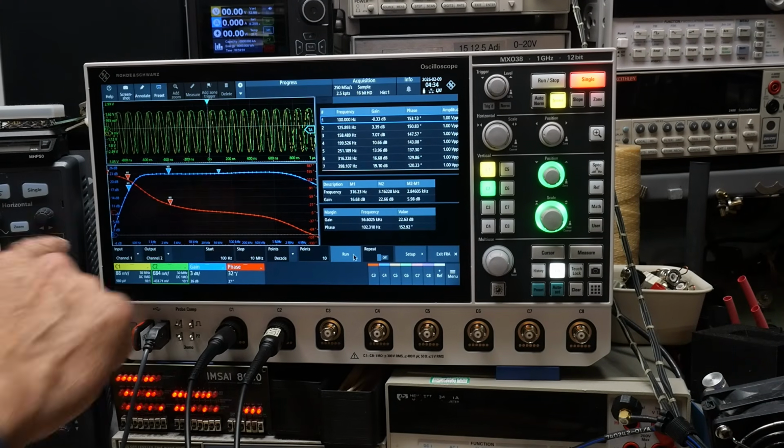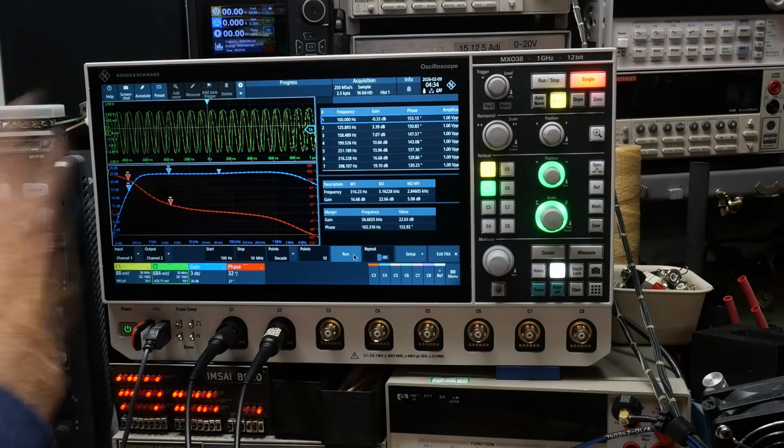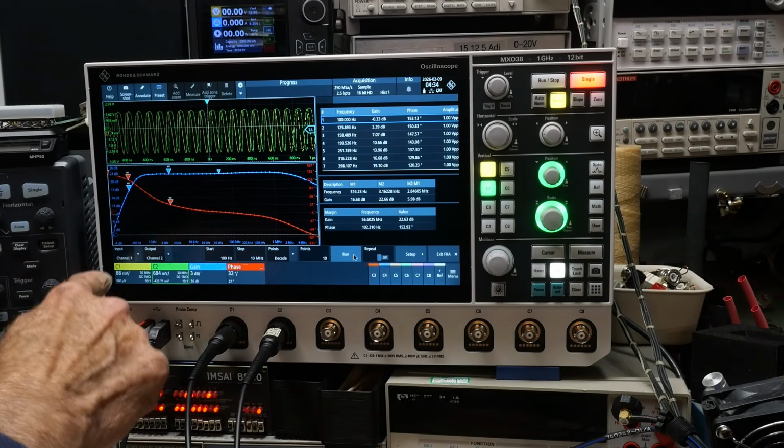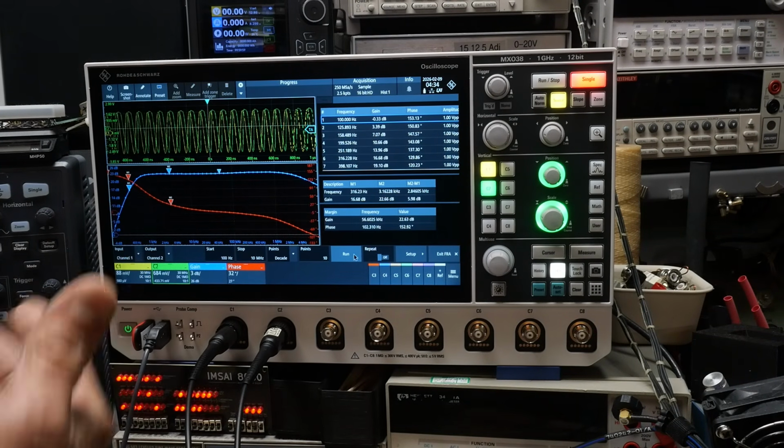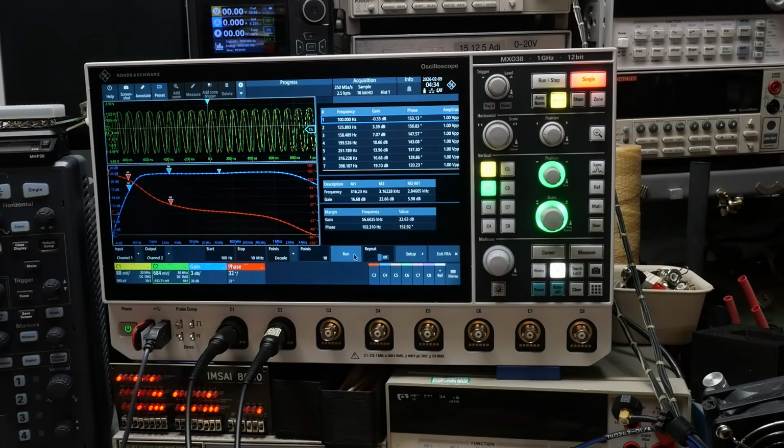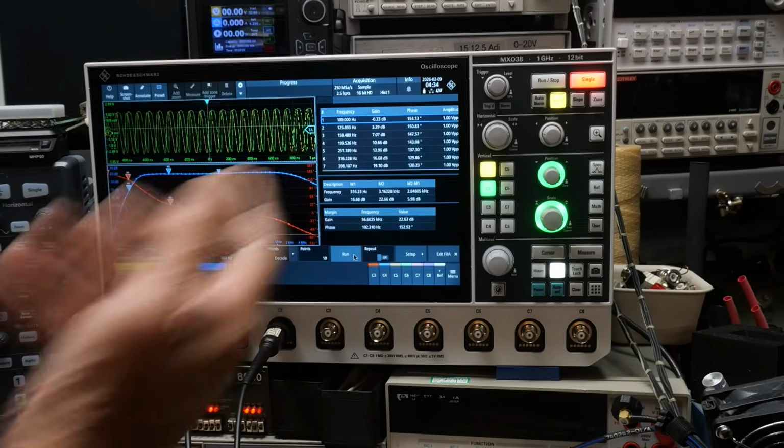And there we go. This is the gain. The gain falls off because it's capacitively coupled in. You need to get a certain frequency before you start getting into the device. And then the amplifier itself starts rolling off past 1 megahertz, right?